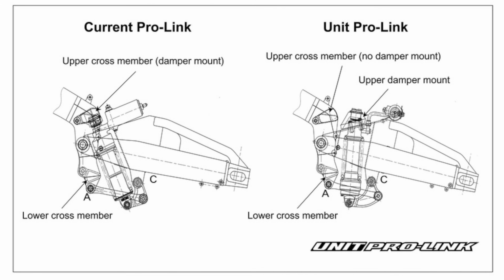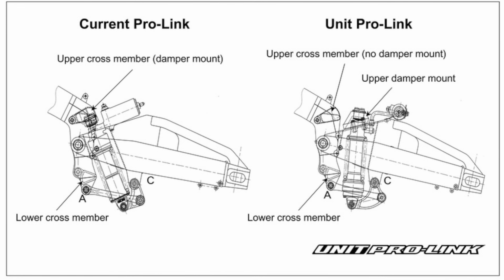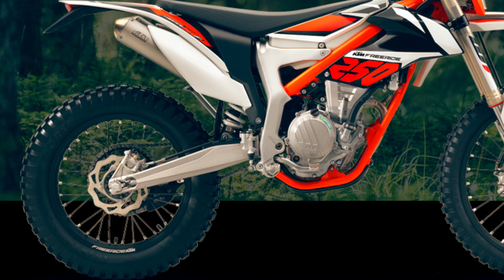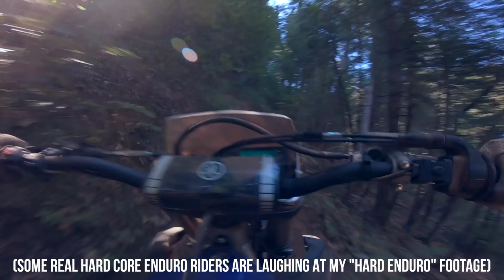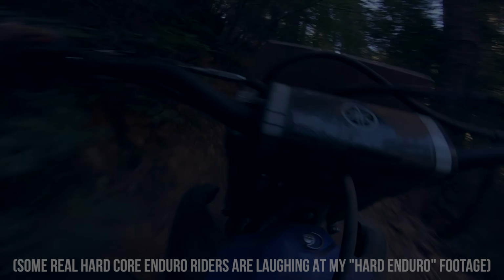All the manufacturers have a slightly different name for their specific systems, but they all work in basically the same way. There's not really a substitute to linkage rear suspension for racing. There are some rare cases that can be made for hard enduro bikes where mass is very important and the speeds are low. There, a simple swing arm can be used with progressive springs.